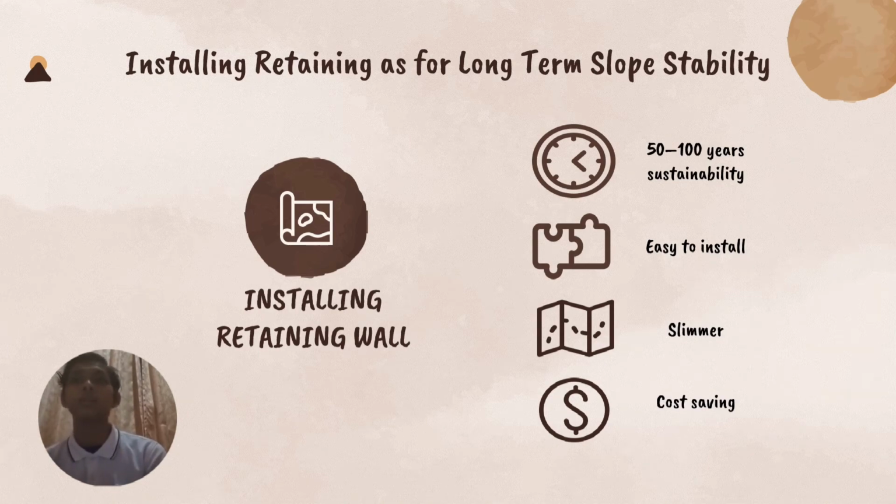To strengthen the point given, for a permanent structure, the general lifespan of a retaining wall is between 50 to 100 years, based on Muhammad Mukhlisin from Polytechnic Negeri Semarang. But the lifespan of the retaining wall mentioned depends on the condition of the soil. Results show that higher soil moisture content, soil density, soil thickness, and smaller soil particle, as well as steeper slope gradient, resulted in deeper soil settlement and greater potential for slope failure.